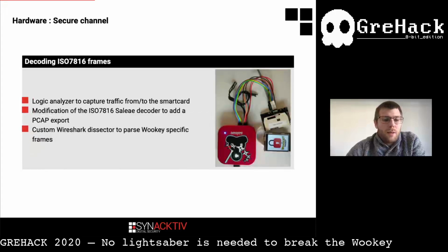The first hardware test we did was the analysis of the secure channel establishment. This channel is established between the Wookey and the smart card to exchange sensitive data. The objective of this test is to see if the Wookey respects its documentation. We used a logic analyzer to capture the frames that come from the smart card and the frames the Wookey sends to the smart card.